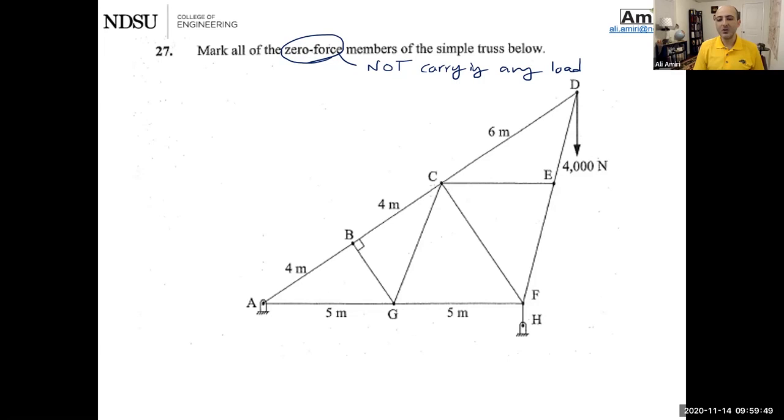So someone might ask, what are the reasons we include them in a truss? There are 2 reasons. One is sometimes for construction it's needed. Second is if anything on the truss loading changes, those members that are not currently carrying load might come in and help and carry some load. So that's for change of load and also construction.